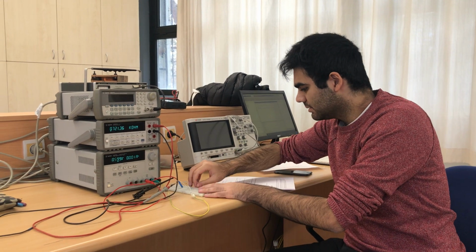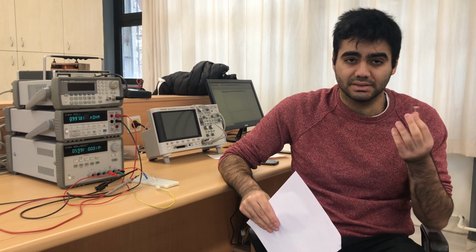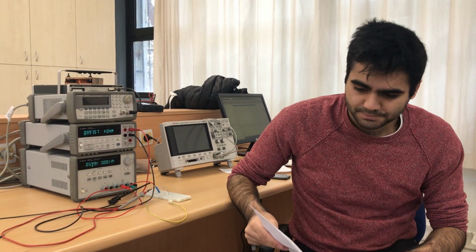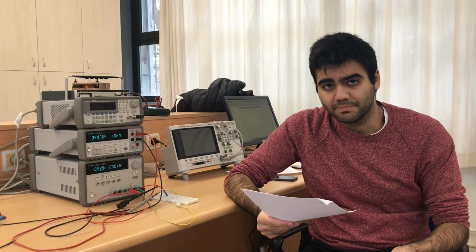So in the preliminary work, I want you to do research about light dependent resistors. Here is a light dependent resistor, and let me explain it very quickly. A light dependent resistor is a type of resistor, and its resistance changes with the light intensity. And light intensity depends on the distance from the light source. So by using this information, we will try to make a distance sensor. And in step 2, we are going to analyze that.